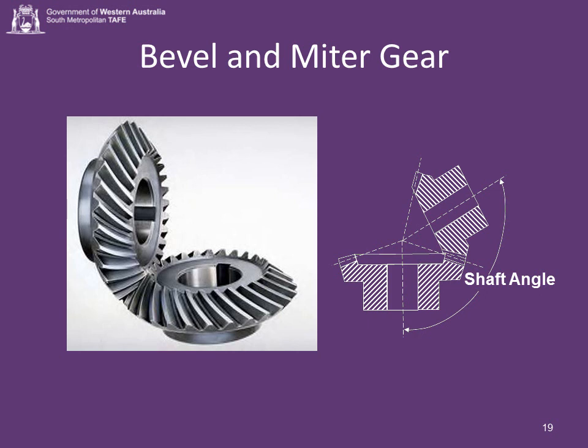The diametrical pitch number, as with spur gears, establishes the tooth size of bevel gears. Because the tooth size varies along its length, it must be measured at a given point. This point is the outside part of the gear where the teeth are largest. Because each gear in a set of bevel gears must have the same angle and tooth lengths as well as the same diametrical pitch, they are manufactured and distributed only in mating pairs. Bevel gears, like spur gears, are manufactured in both the 14.5 degree and 20 degree pressure angle design.